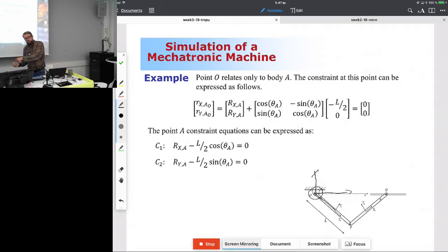Always the body reference coordinate system, and then wherever you want to go within the body, no matter where they are located. Don't try to be smart. Don't try to make shortcuts. They will not help you at all. Okay? So I first travel to the body reference coordinate system, which is defined by this vector here. Then I account for the orientation of the body reference coordinate system by a 2x2 rotation matrix. All right? Then I'm now here, in this coordinate system, and I have to go back to the origin of the global coordinate system, which is the point O.